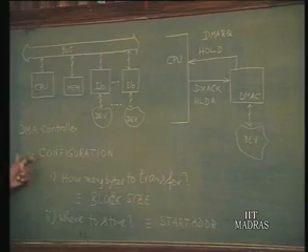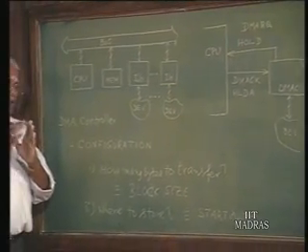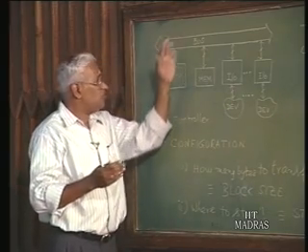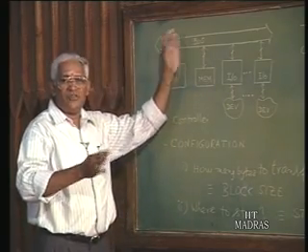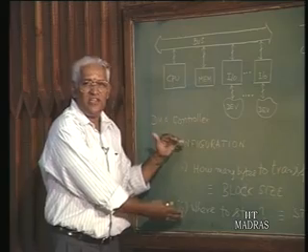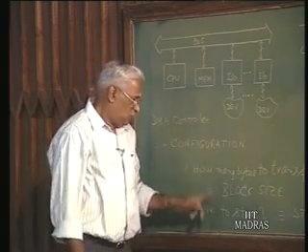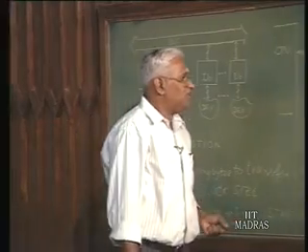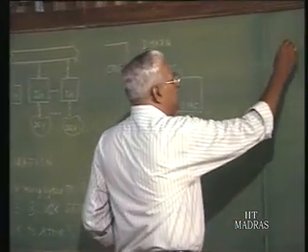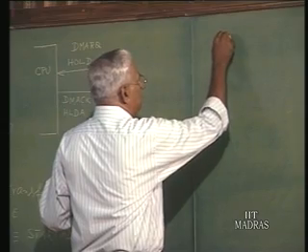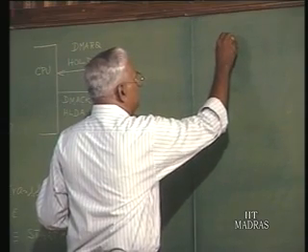So, these things must be stored in the DMA controller, and that will be done by the CPU during the configuration phase. Now, we always said that I/O consists of the configuration phase and data transfer. Since the CPU is not involved in the data transfer, the CPU's job is over with the configuration phase, because that is all the CPU is involved in. So, these two things, what is it like, let us say for instance, as part of the configuration, the software segment would be something like this,